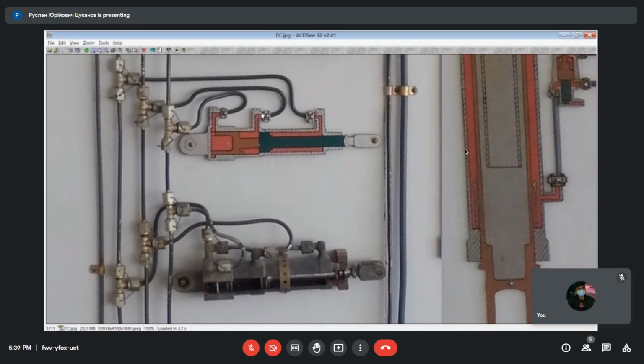In this situation, the middle you also attach to the return line. In this situation, fluid which comes from the left presses the floating piston to the right, and the floating piston comes to this stopper, because the change in diameter doesn't allow the floating piston to go to the right further than this point. As a result, the floating piston, which has bigger area, forces the piston attached to the flap to the right, but not to the extreme position, but to an intermediate position. And so the flaps will be in the intermediate position, takeoff 25 degrees.